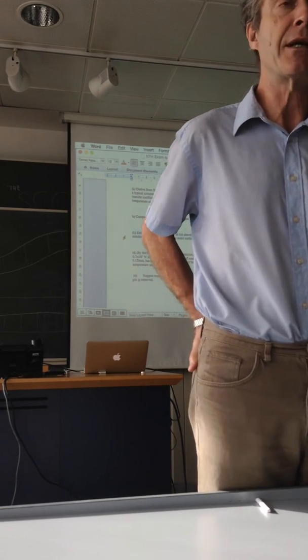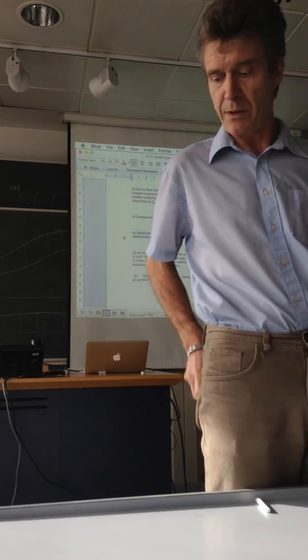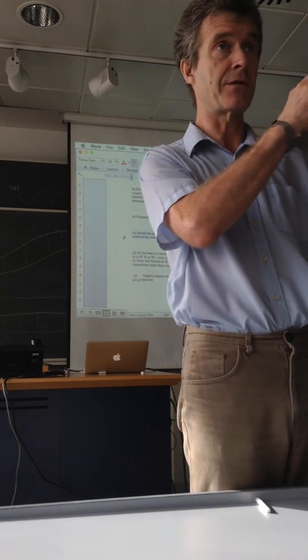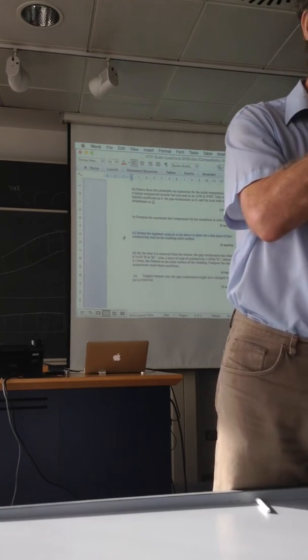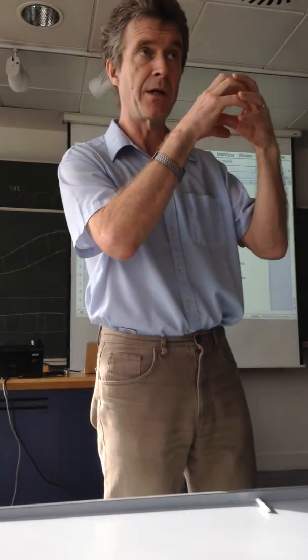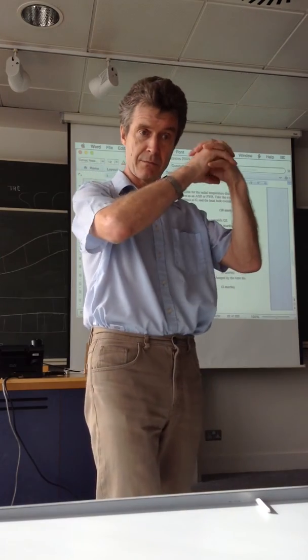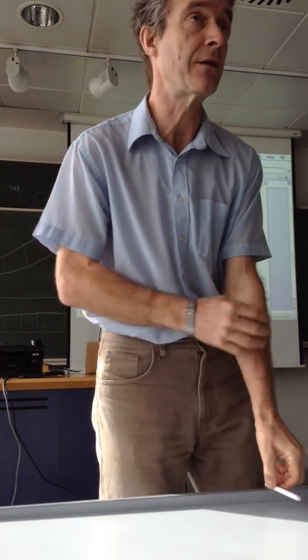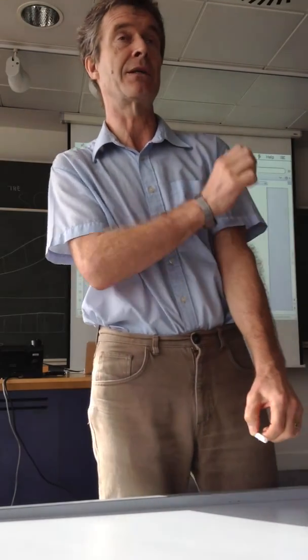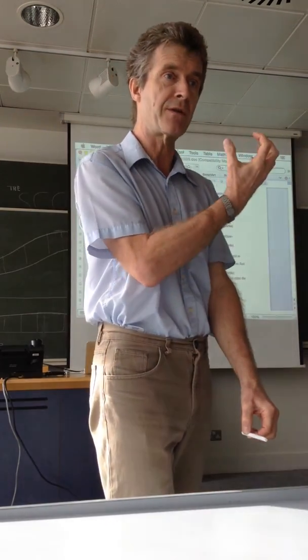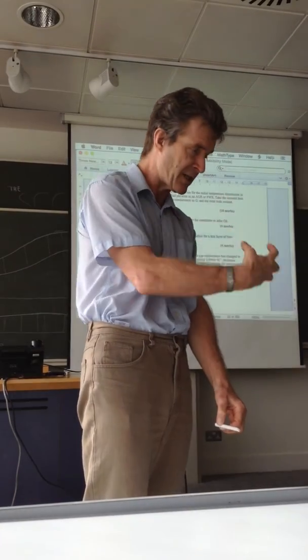Bubbles at enormously high pressure, because they're trapped by the surface tension of the solid. Solids have surface tension just like liquids. So whatever the surface tension is, there's a 1/r dependence of the pressure that is formed by that surface tension. So you get gigapascal pressure bubbles trapped as small bubbles within the lattice. So very, very small high pressure bubbles that migrate as bubbles then.